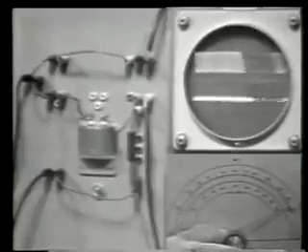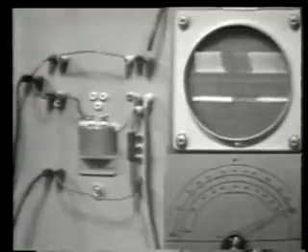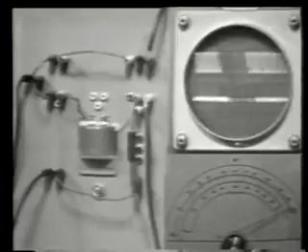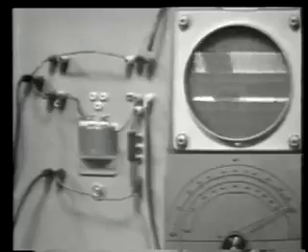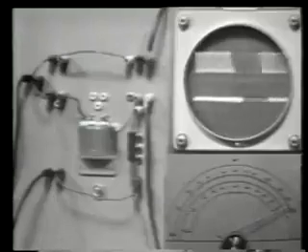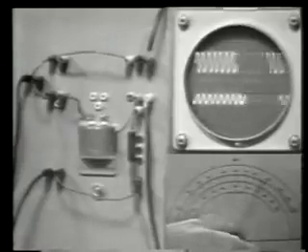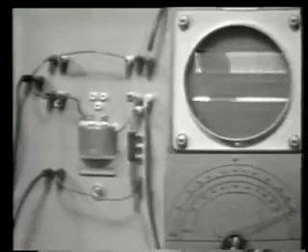Here at about 1200 hertz, you can see that I hardly have anything at all in the output, so we're rejecting these higher frequencies. With a 10 Henry inductor and a 0.01 microfarad capacitor as my filter components, I'm passing all frequencies from about 1 hertz on up to about 600 hertz, on up to about this point. But those frequencies above 600 hertz are not getting through. They're being rejected by our filter circuit.